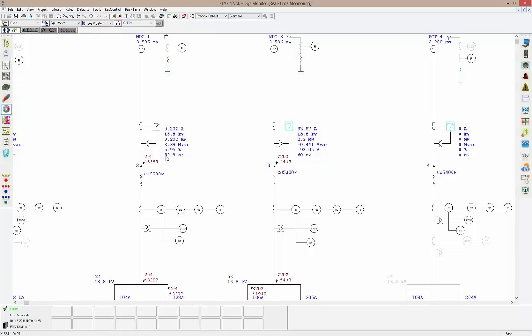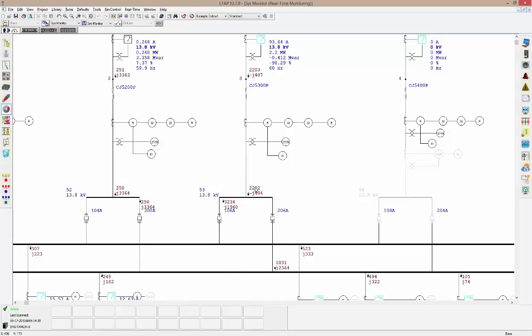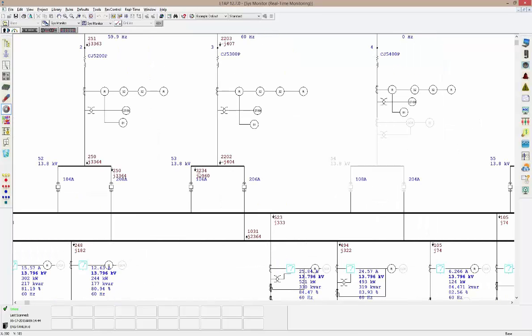So here we can see in blue again is my meter measurement, and in this reddish brown color I can see my state estimator output. And what we notice here is I have a flow shown on my 13.8 kV bus, and there's a flow shown on the 2 breakers that leave this particular cable in the system. So I have about 3.2 megawatts and about another megawatt here circulating through this bus bar section. And this circulation is actually being shown